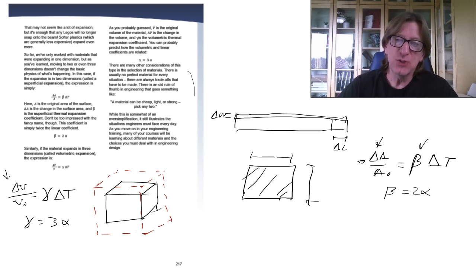So there's always trade-offs in choosing a material. Legos are extremely light. And so therefore you can get more power, more velocity, for example, out of the same motor than you could with a heavier aluminum. However, as we've seen, they're not as strong. So the adage in engineering basically is a material can be cheap, light, or strong, but you only get to pick 2 of them.